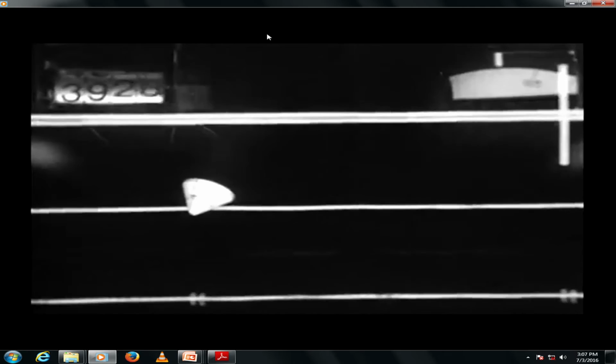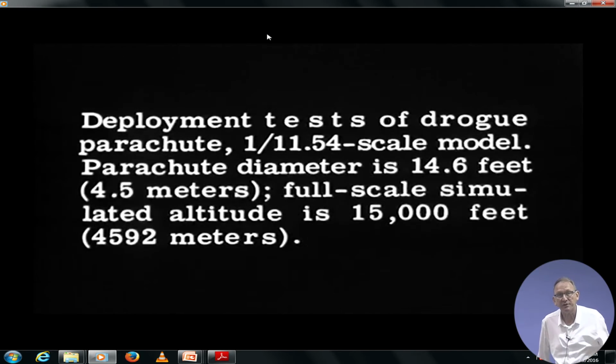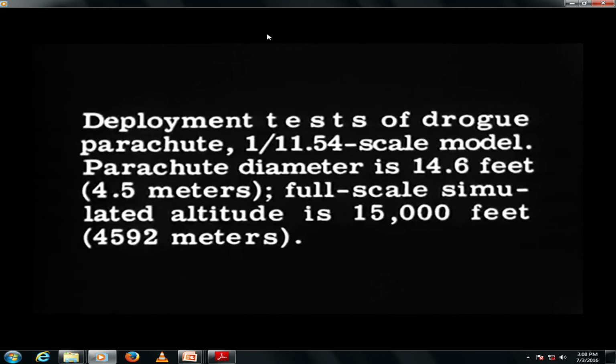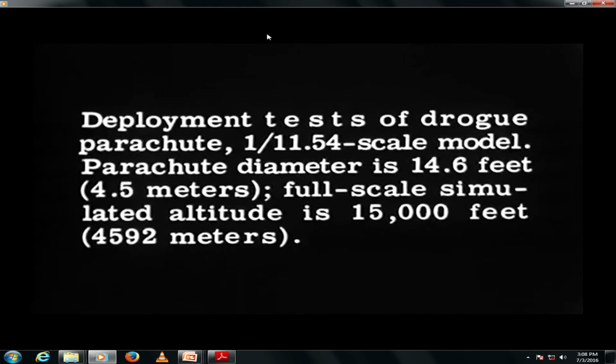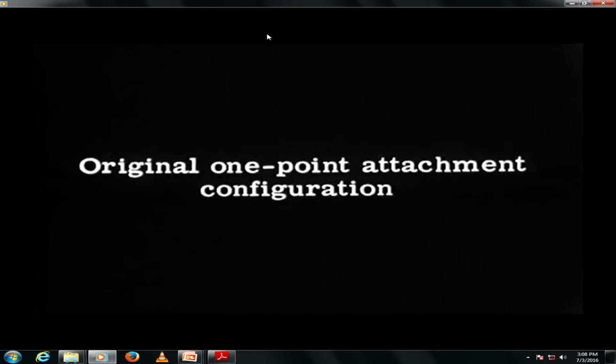Of course, it has to be simulated in terms of mass, moment of inertia, to simulate scale down to the model. Once it is dynamic testing, you have to simulate your dynamic features of the model. Usually you just simulate the shape of the model because you need to know the aerodynamic coefficients.